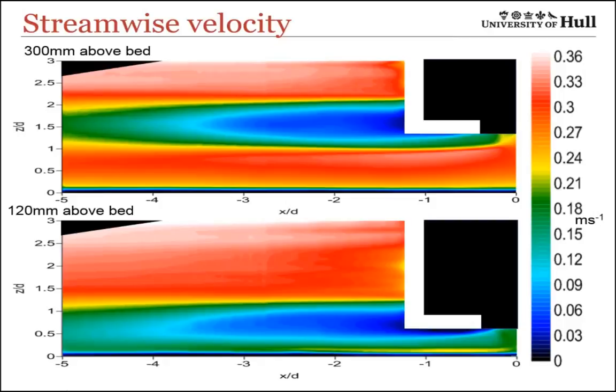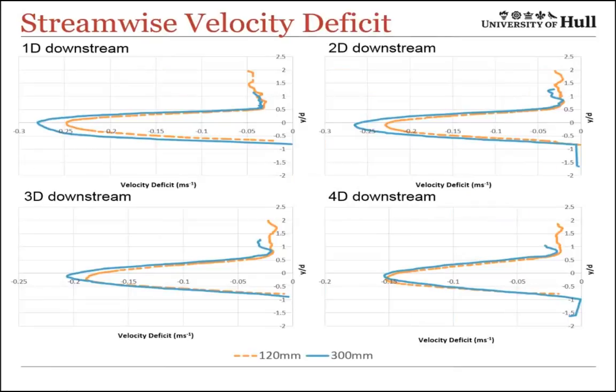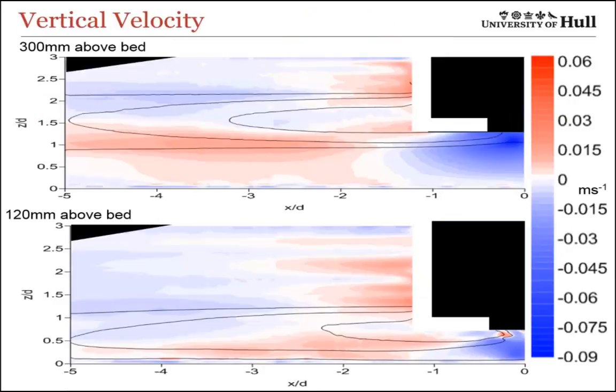Higher in the flow, that narrowing happens much more quickly, so the diameter of the wake is reducing more quickly downstream. Of course, we're able to then look at velocity deficits from the plain channel run, to look at how far downstream these sorts of effects are mitigated or carried, just to give you an idea of the sorts of impacts that those turbine devices have at different elevations, and actually quantify something that we can non-dimensionalize and begin to play with in terms of looking for patterns within positions and tip speed ratios, etc.